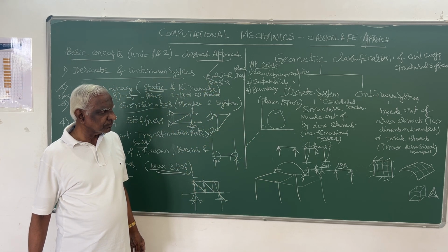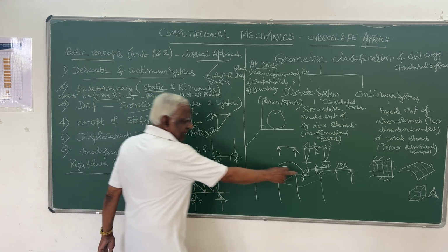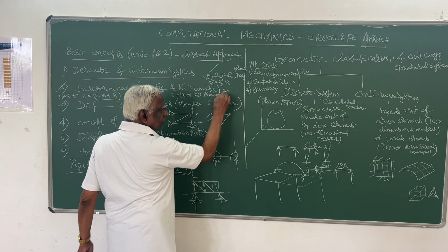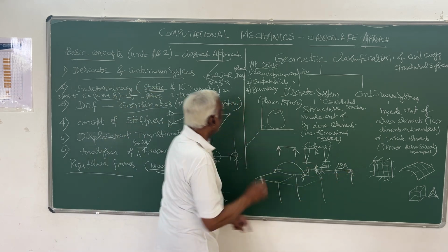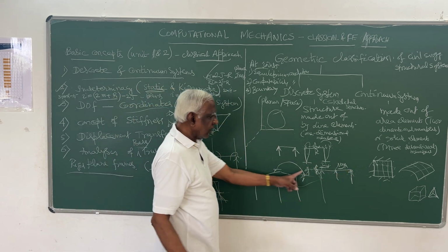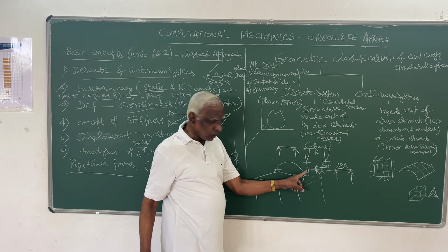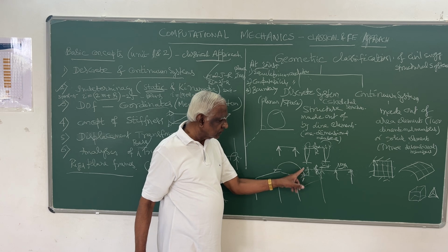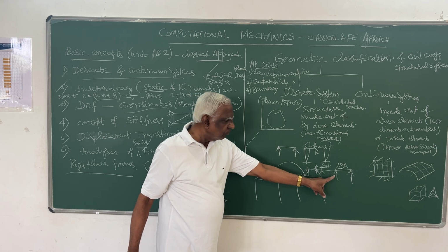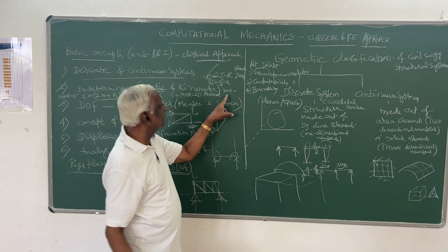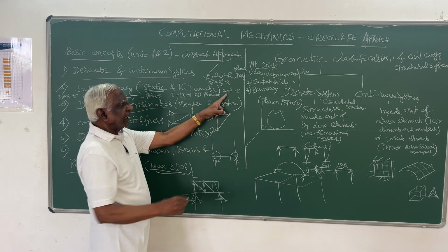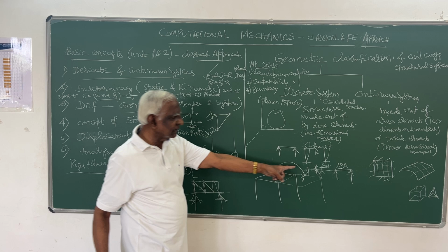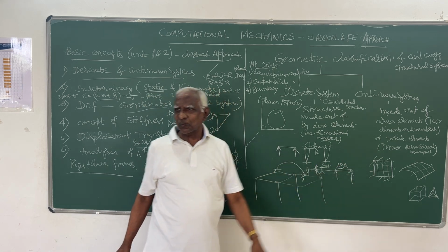Right? So 8 minus 5. So 2j, 2 into j is 4, minus r, 2 reactions. Though you have 3 here, axial reaction we neglect, I told you. So 2, 3, 4, 5, minus 5. So 8 minus 5, 3. Kinematic indeterminacy is 3. That 3 is these rotations.